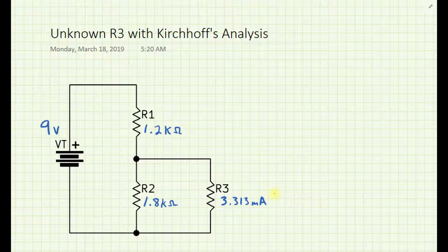So let's just take a look at this and see what we're going to do. The first thing that I'll do is I fall back on my Kirchhoff's laws. So I look at loops and try to see the voltage relationships. I'll create a Kirchhoff voltage loop equation for each loop and explore those relationships, and then I'll look at my nodes.